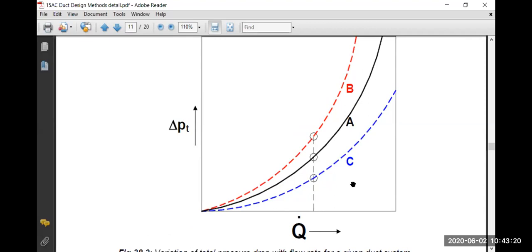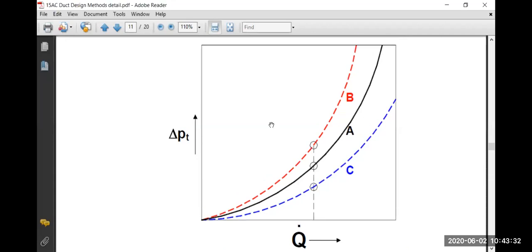Now, having the knowledge of using these instruments after installation, a separate engineer, called the commissioning engineer, measures each and every thing, each and every place, these flow rates. So once you know this flow rate versus total pressure drop, you can draw this curve. This is a hyperbola, curve A. This is designed by the engineer before installation, before the project is commissioned.